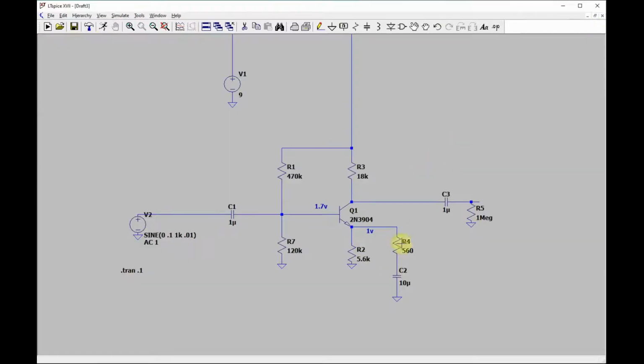So you can even put a pot on here that goes from 0 to, if you make it 5 or 10 times this, then when we turn it up all the way, the circuit really doesn't see this too much, and you can bring it all the way down to pretty low. I usually make it about 5 times this one here, usually a trim pot. Make it about 5 times greater than there, and the circuit sees a little bit extra gain, but you can adjust it up and down.